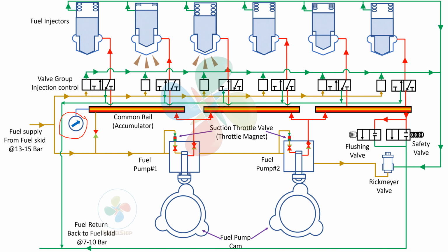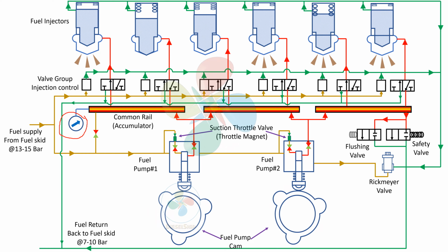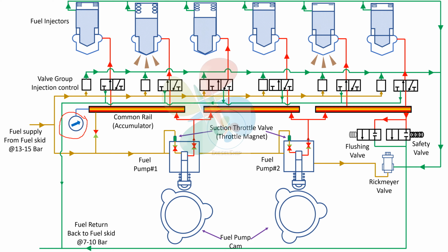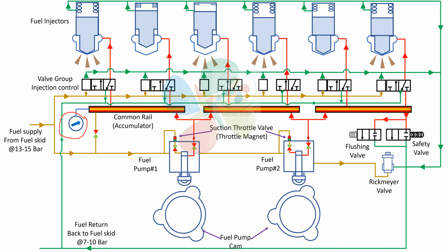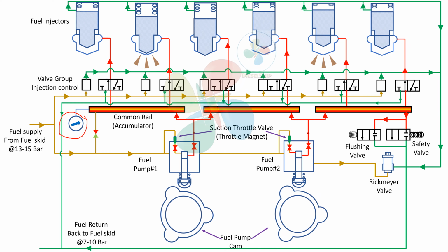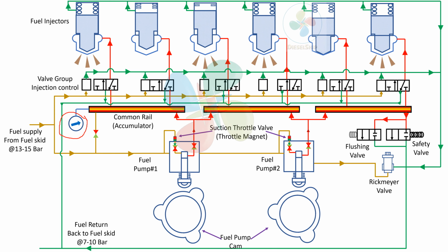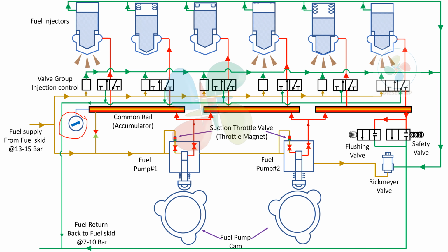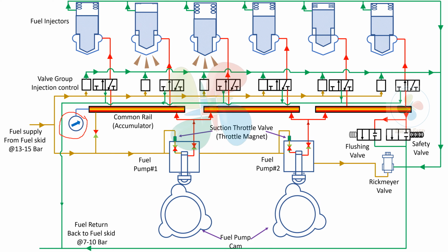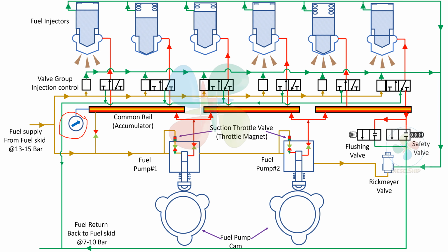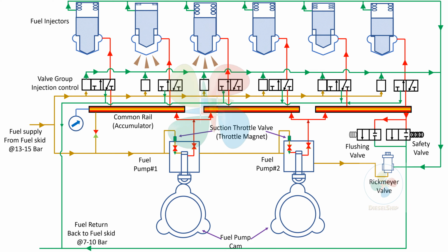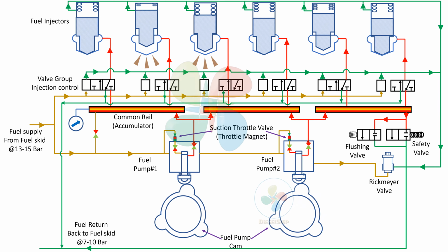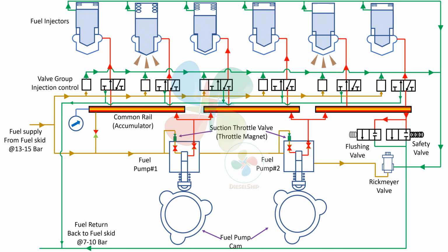I've tried to capture the closest to the exact timing, but you might see some lag here and there, especially in the springs. I've tried to simulate different ways, but this is the best I could do. I hope that doesn't really affect the functionality, and I'm sure you are able to follow the diagram and understand how the complete circuit works. In the next slide, I'm going to explain the fuel timing. Right now what you're seeing is the control of the fuel quantity, precise metering, and termination of injection. Everything is shown here. In the next slide, we'll see the timing.